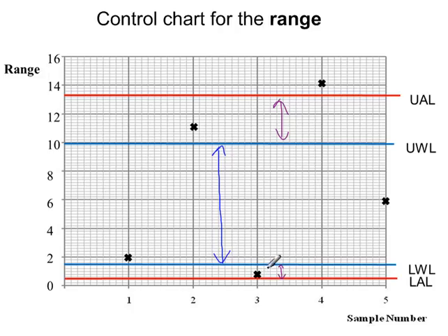We're looking at a situation where we want to maintain the improvement. That one's too high. It's above the action limit, so stop the process and take action immediately. And this one's within the warning limits, so this one's fine.